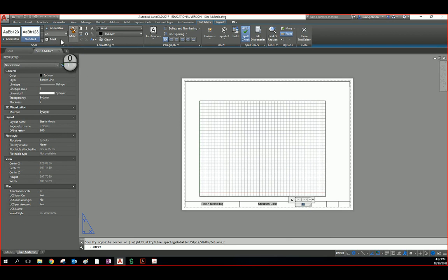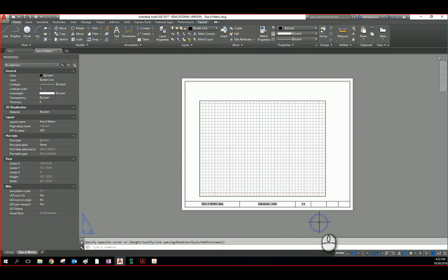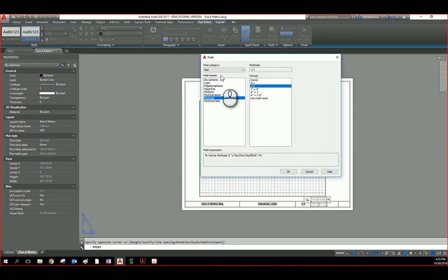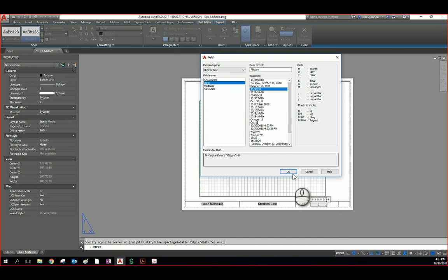Prior years we had problems where kids would make a drawing and then print it, fitting it to scale or fitting it to the sheet. And it's a bad principle to do that, mainly because the whole point we're trying to grasp to you guys when it gets to using AutoCAD is the difference between paper space and model space. It's important to know that, because if you go into the field of architecture or any type of engineering, you're going to need to understand how to scale drawings appropriately.